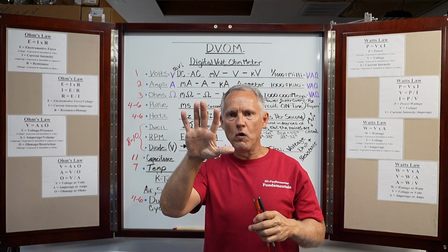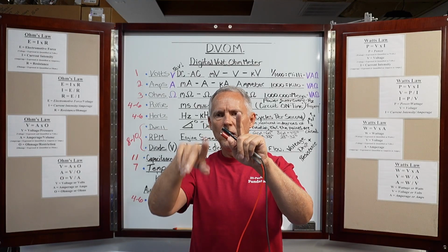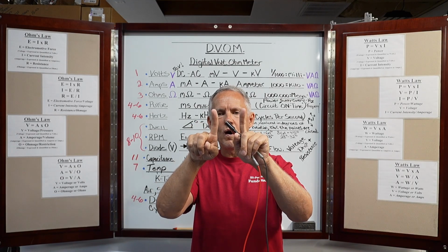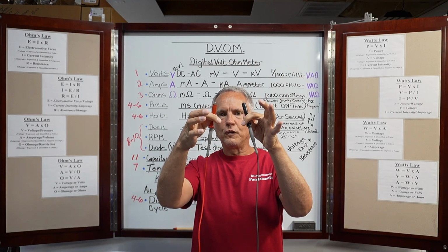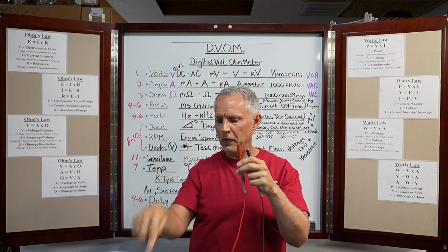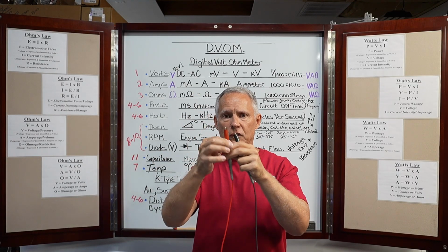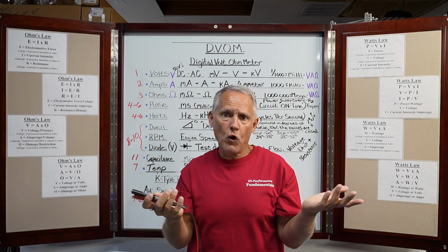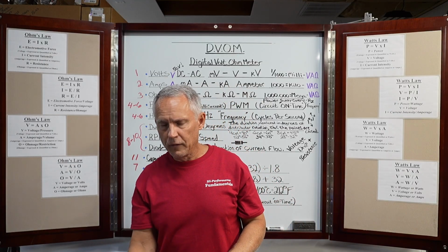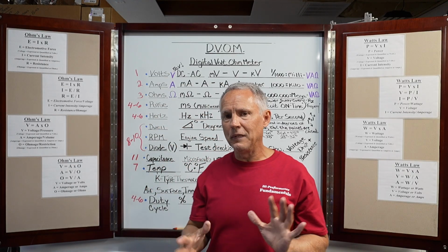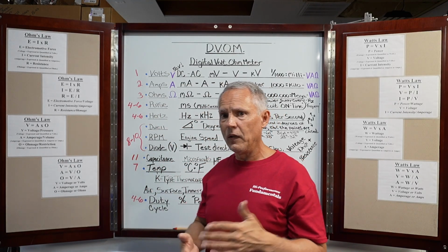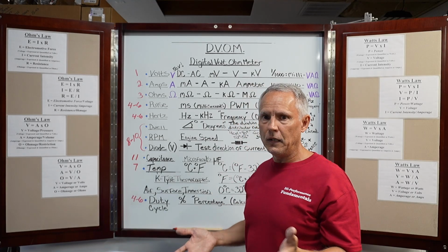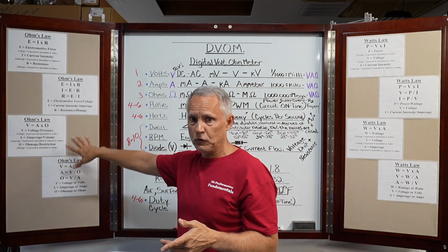Let's say you had a fan motor, and you had a power wire going to the fan, and a ground wire or a common wire coming off the fan. One to the other, measure the two. That's the resistance in ohms. Measure it, it will show up on your meter. That resistance is your ohms. Now you've measured ohms. You measured the resistance, right? The meter has the ability to calculate it, but that's how you determine that reading that you're going to need for these calculations.